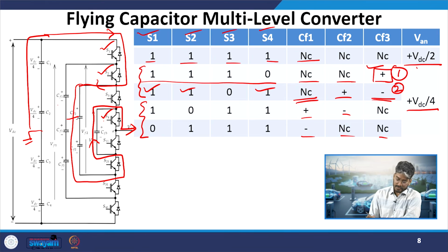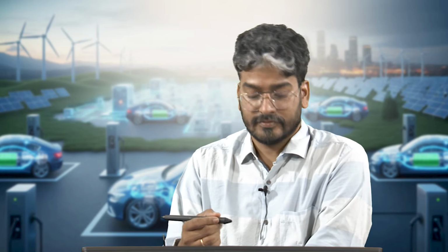Okay. So, we will stop at this point. What have we seen today? Today we have seen multi-level converters which will be used in our charging applications, specifically to develop our DC fast chargers. There we have seen our first diode clamp circuit, which required a quadratic increment of clamping diodes, and it had a limitation of balancing the capacitor voltages connected across the DC bus because there was no redundant combination. Then we have seen the flying capacitor circuit, where we have various floating capacitors in place of the clamping diodes in our previous circuit.